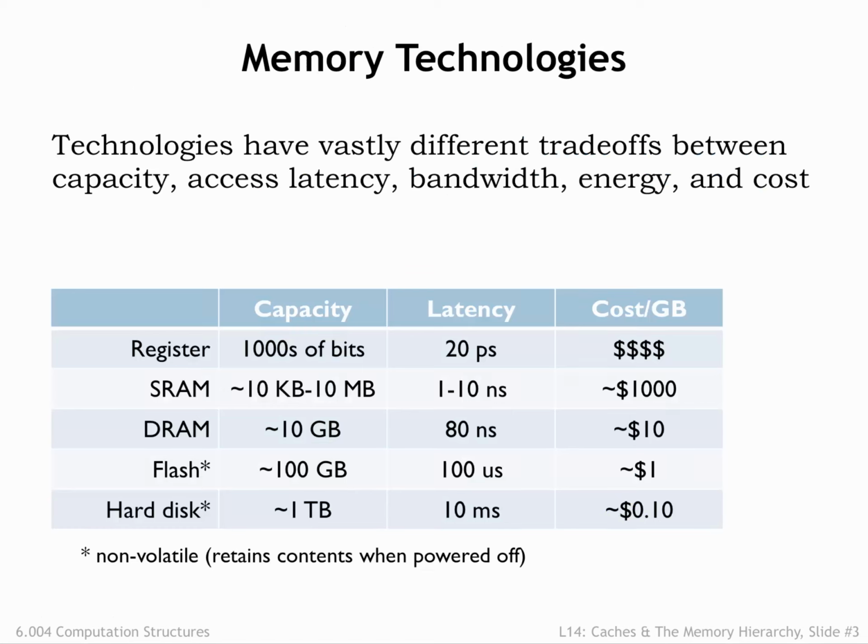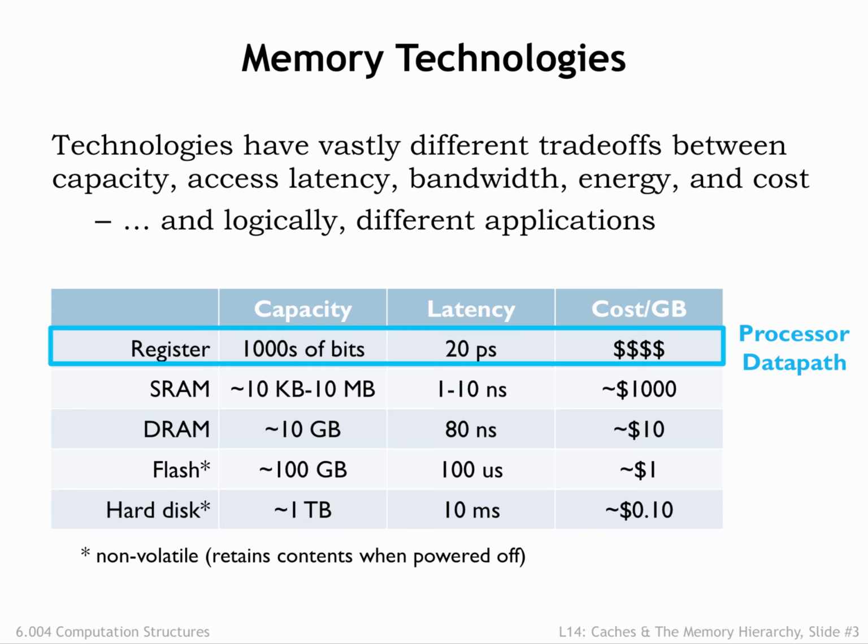We have a number of memory technologies at our disposal, varying widely in their capacity, latency, bandwidth, energy efficiency, and their cost. Not surprisingly, we find that each is useful for different applications in our overall system architecture. Our registers are built from sequential logic and provide very low latency access, 20 picoseconds or so, to at most a few thousands of bits of data.